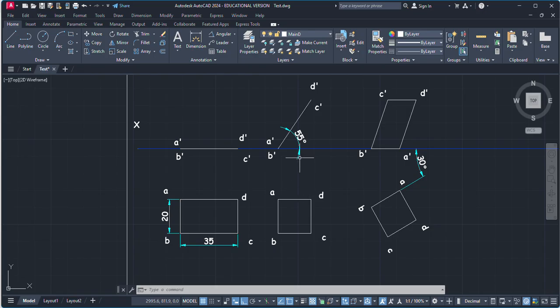So we find out that when we rotate this rectangular surface by 55 degrees with HP, then in the top view we will have a square, and again this is our resting edge, where this point stays on the reference line. Now we have to make sure this resting edge makes an angle of 30 degrees with VP, so